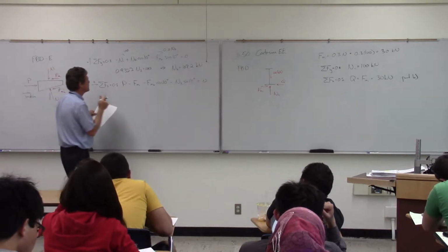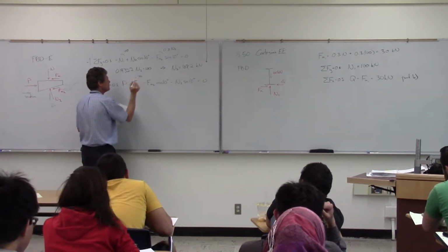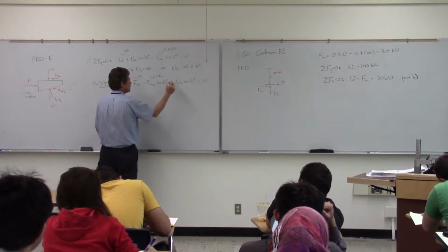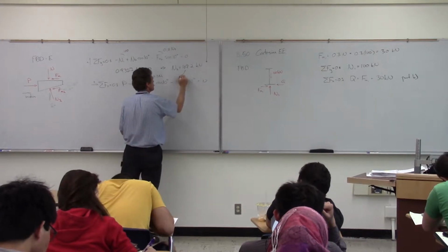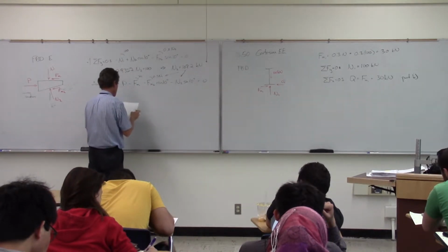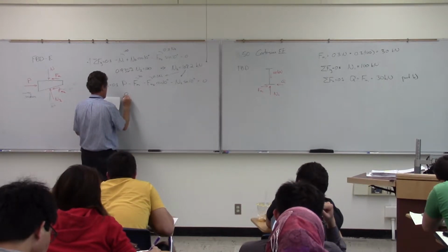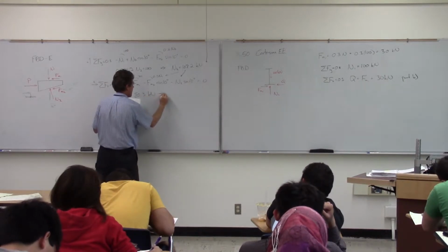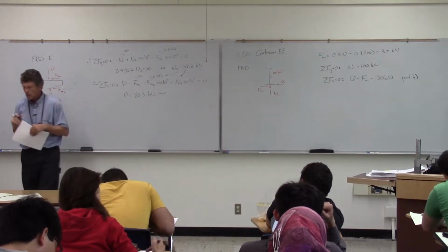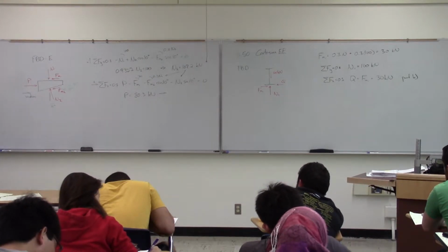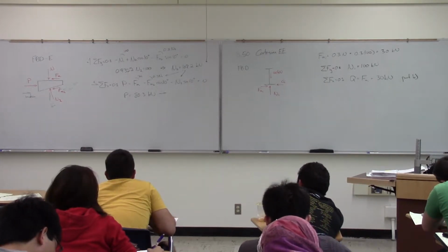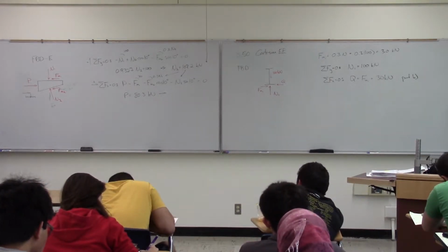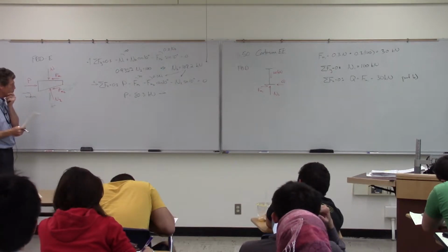And then again, identifying things that we already know. We've got this at 30. This is going to be 0.3 of N2. And we've already calculated N2 as 107. And what we find then, to get that wedge to move, to overcome that friction force now, FM1 and FM2, we need a force of 80.3 kilonewtons to get that going.